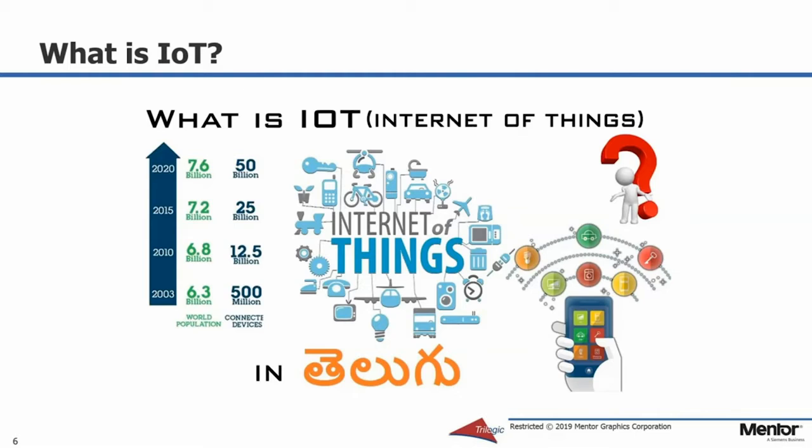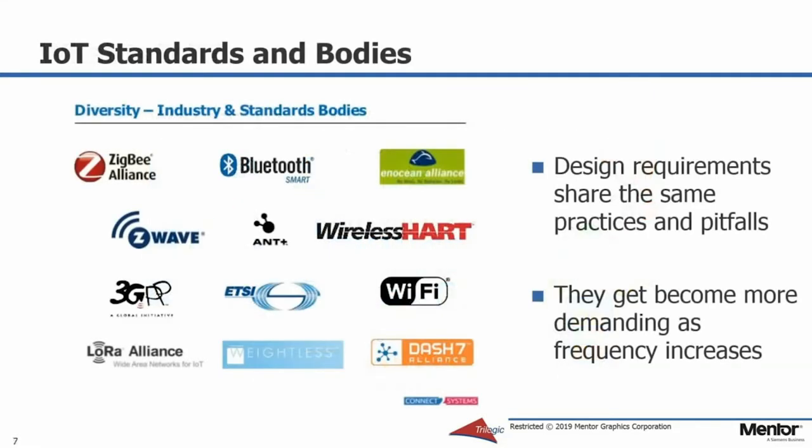It has also increased the need to understand what design requirements will comply with regulatory certification and what oversights may lead to failed tests at compliance test time at an FCC or CE lab. There are several IoT standards being employed today, from Zigbee, Z-Wave, to ANT, Bluetooth, and 802.15.4, as well as LoRa.